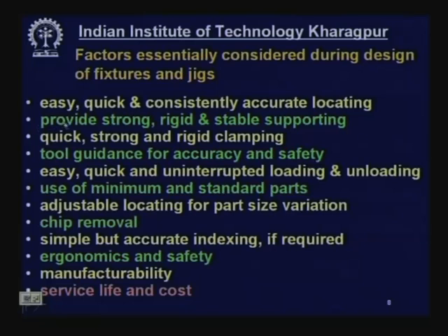Then provide strong, rigid and stable supporting. The supporting pins or surfaces should be strong to counter the stresses. They should be rigid to prevent or reduce bending or deflection, and stable to prevent toppling or shift movement. Quick, strong and rigid clamping.